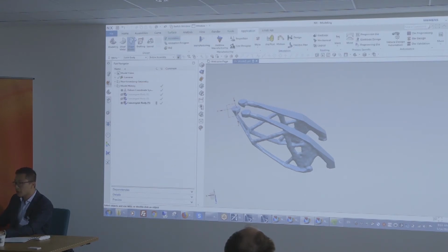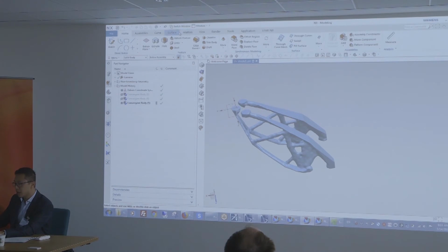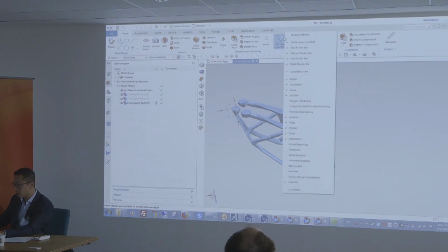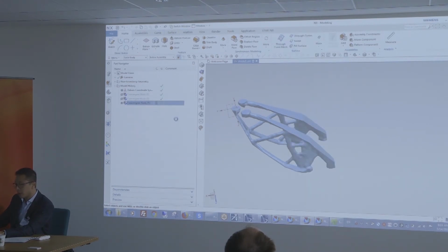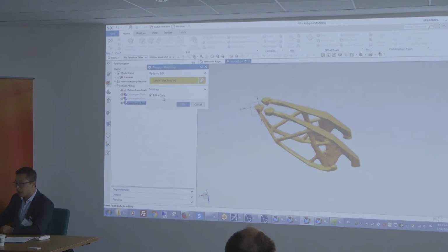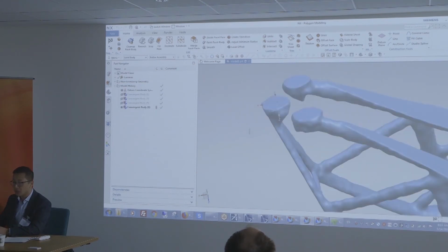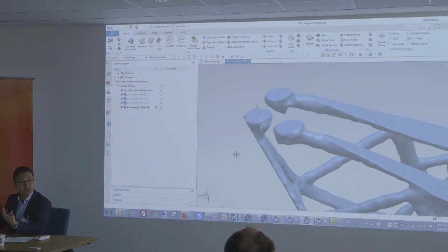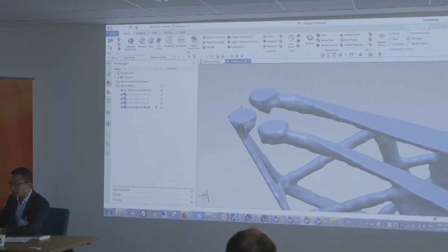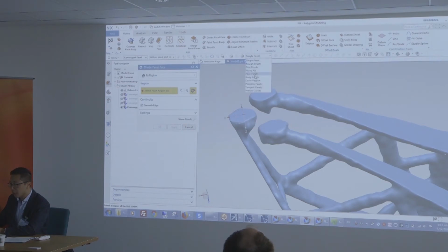Before I move forward, let me just show you one more thing that you can accomplish using this. So if I go back in my polygon modeling environment, at this point, as I've mentioned, this is one large surface. It's a face-set model. If I want to create features on it, I need faces. I need physical B-rep surface on it. So what I can do is use these tools to split my face-set geometry quickly.